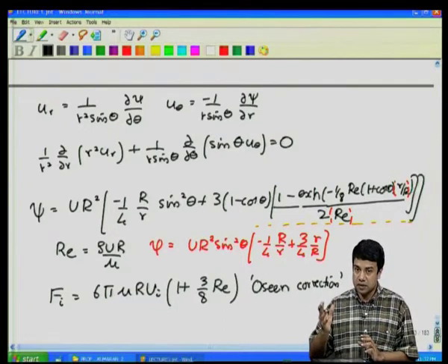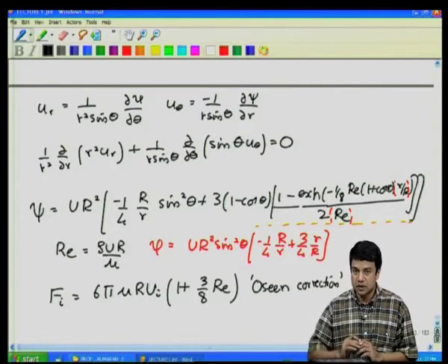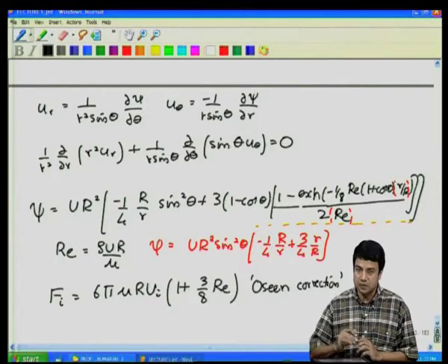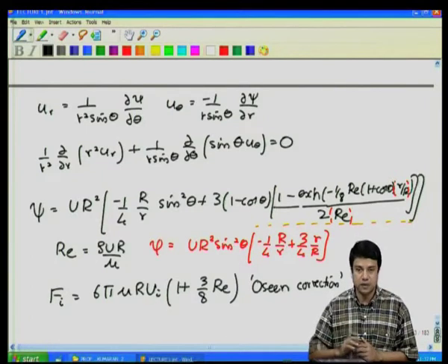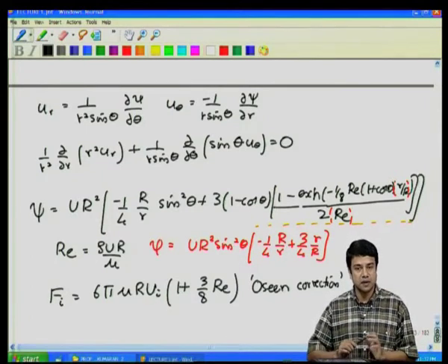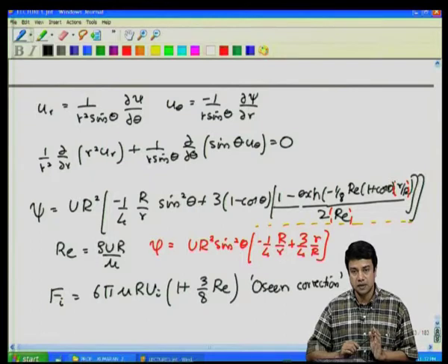Once you go beyond that, inertial terms do become comparable to the viscous terms, and you can no longer neglect the inertial terms of the conservation equation. However, even though you cannot neglect the inertial terms, you can still reduce it to a linear equation, the Oseen equation for the velocity profile. This is still linear in the velocity u prime, but it is no longer reversible because it contains capital U dot grad of u prime. So, it is no longer reversible, but it is still linear.